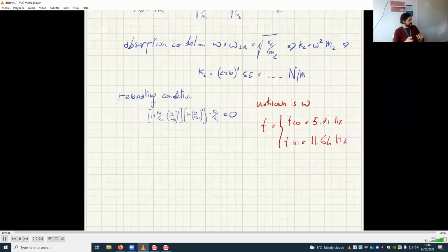The shaking like crazy is because there is no vibration absorber, but the natural frequencies of the crankshaft, the first one is always lower than the RPMs you get in general, because it's designed on purpose like that, because you are never supposed to be at that low number of RPMs. When you are at that low number of RPMs, it's shaking like crazy because you're hitting the first natural frequency of the crankshaft.